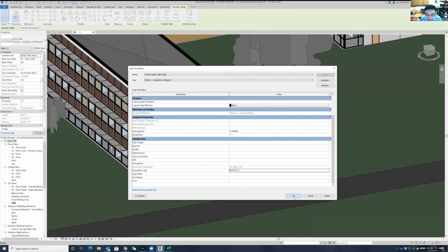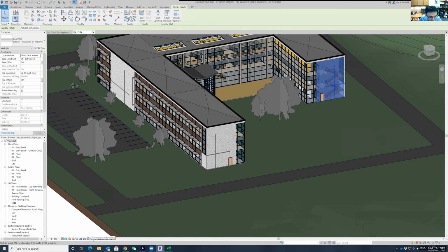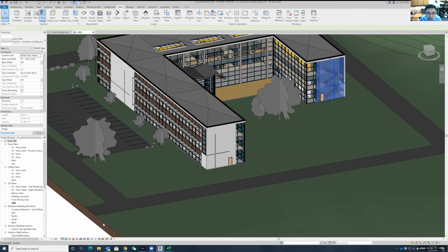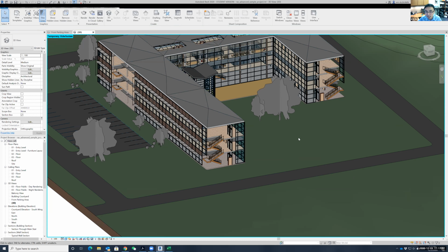So guys, since this is the type tab, which means what? Which means the same type will be assigned with the assembly code already. So let me click this wall and go to the Edit tab. See, it has the assembly code already. So how can I tell which has already been assigned with assembly code? I can just use the hide category function. So I select this one, which I already assigned assembly code to. I use this little pair of glasses and choose hide category. Then all the same type of wall is gone. It's okay because I already assigned assembly code to them, right?